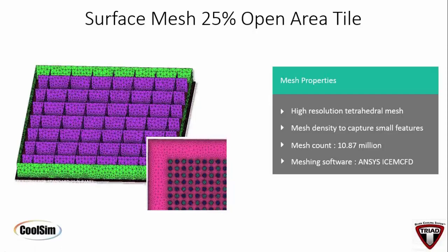Yeah, I was breaking up a little bit there. What happens with the flat bottom is the air flows across, and that's what's causing some of that short cycling you're seeing. But the structure, either they have this kind of egg crate look, or some of them actually have a dimpled cupcake look to the bottom of them. Right. And what that does is it creates a turbulence right there. Yeah. And what we're trying to do is get a laminar flow at the bottom of the tile, directing it upward to change it to a turbulent flow within the cold aisle itself.